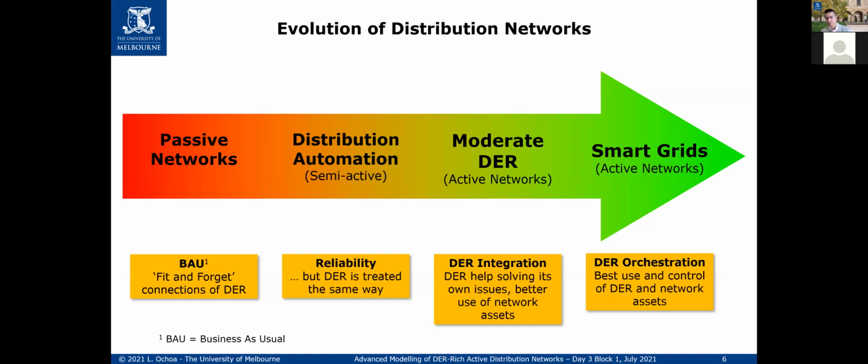They are trying to inject power because the system operator needs a lot of power at a given moment in time. So if this needs to be done in 5 minutes, it means that your control cycle has to be at least 5 minutes. But if this needs to be done every 10 or 20 minutes, then again, your control cycle might be a little bit longer. So it all depends on what you're trying to achieve. There's no single answer here.